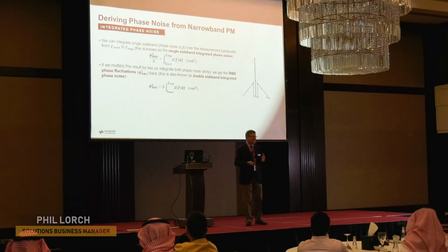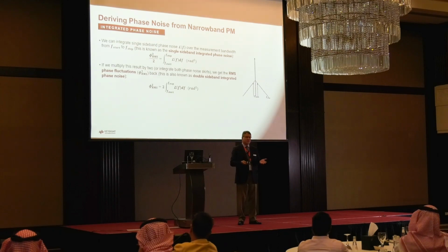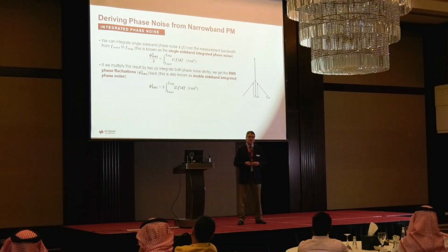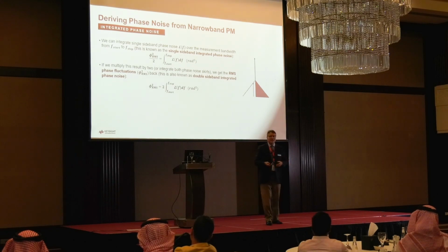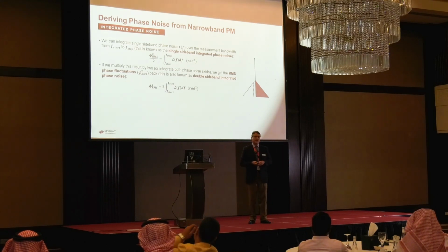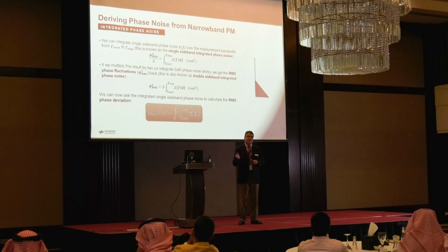If we now integrate all of those amplitudes on the upper sideband, lower sideband, we can describe the single sideband or the double sideband integrated phase noise. And that is another measurement that we can make very easily with our measurement equipment. As another way of describing the noise-like considerations on my carrier frequency. So it's basically just measuring all of the power under those side skirts. And there you have the other formula to get from that measured power back to the RMS phase deviation.